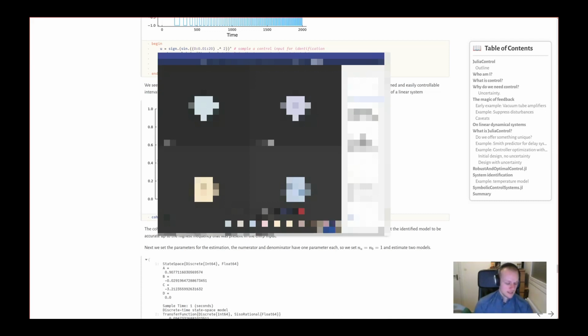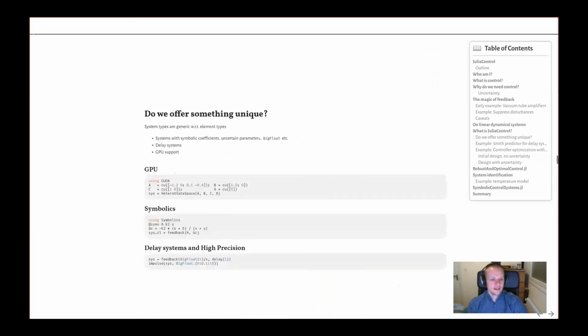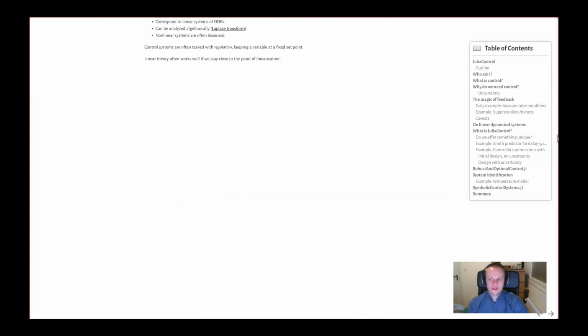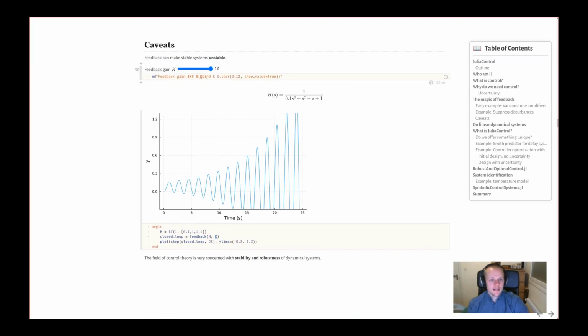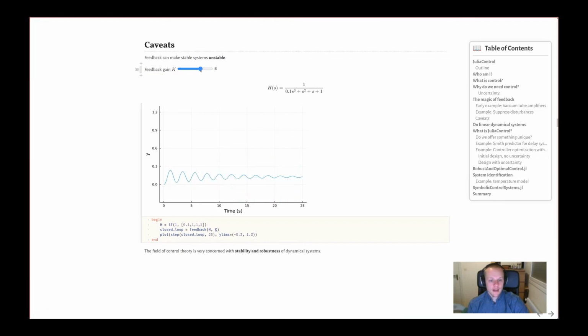Another thing I see is that MATLAB provides a lot of graphical apps, graphical user interfaces. But if you have Pluto, I can go back to this little plot here where I showed the slider. Where did I have it? Let's see. Here. Here I have produced a little plot. So I create a system. I plot the step response. And K here, this parameter K, it's set by this slider. So here I say bind K to a slider. And then I automatically have an interactive app.